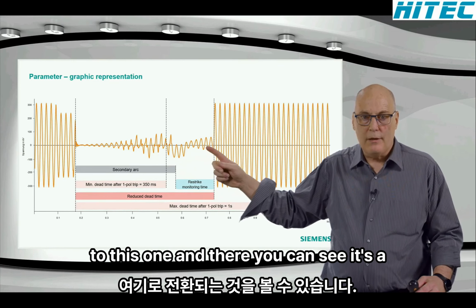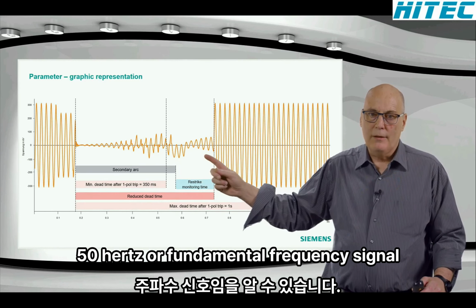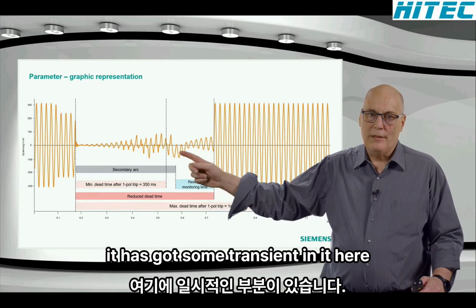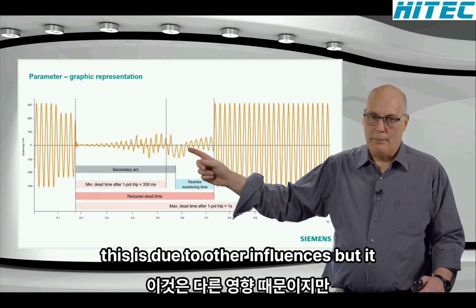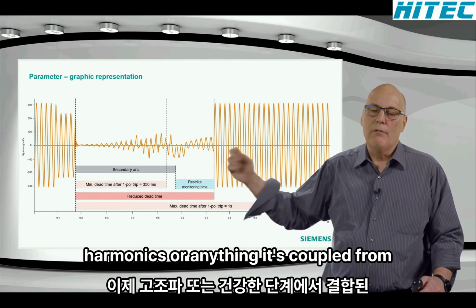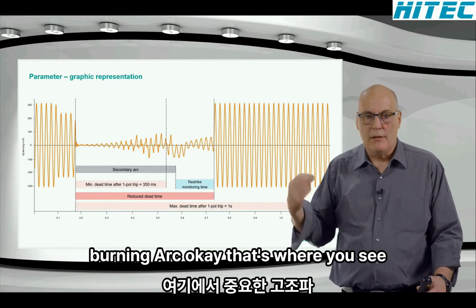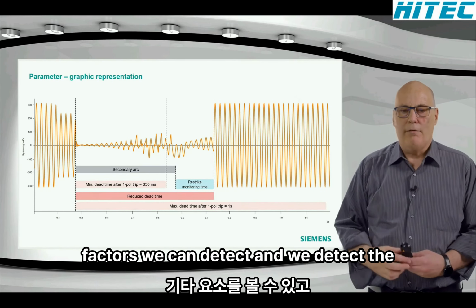And there you can see it's a nice 50 hertz or fundamental frequency signal. It has got some transient in it here. This is due to other influences, but it is a clean signal. Hardly any harmonics or anything. It's coupled from the healthy phases. Over here, it's a burning arc. Okay, that's where you see the significant harmonic and other factors we can detect.